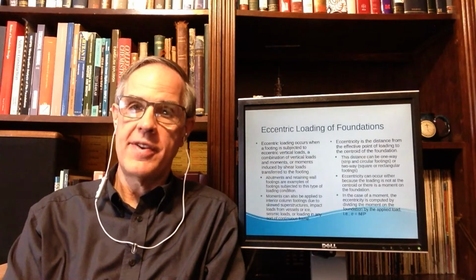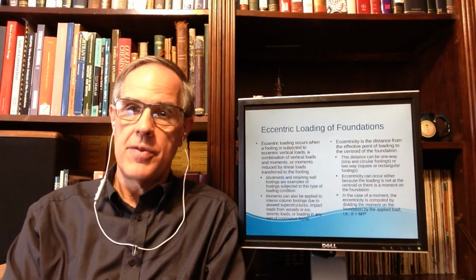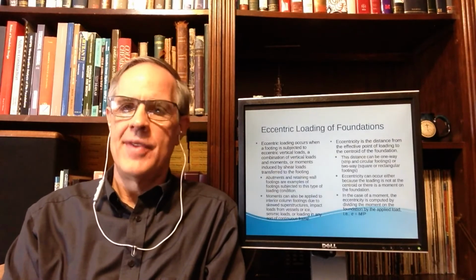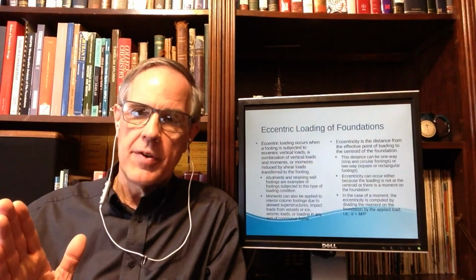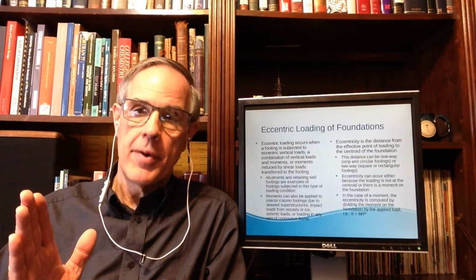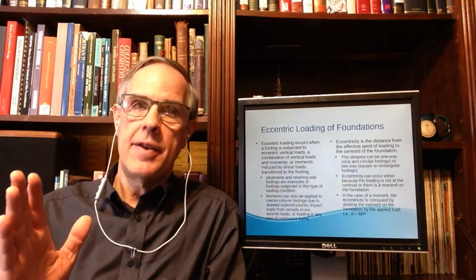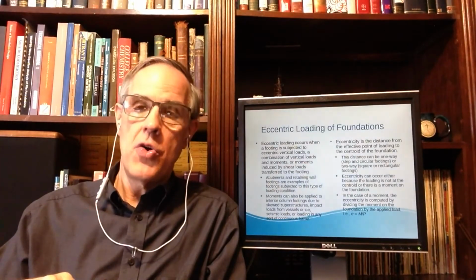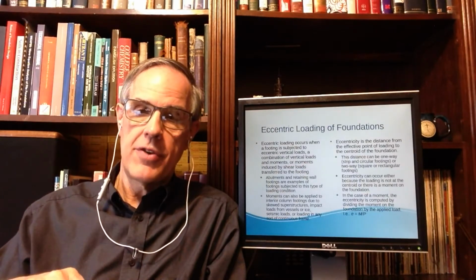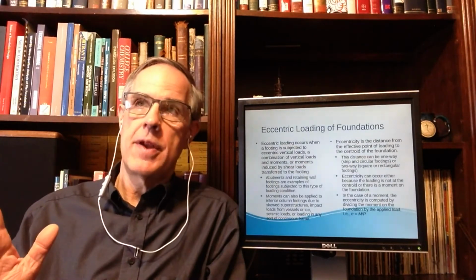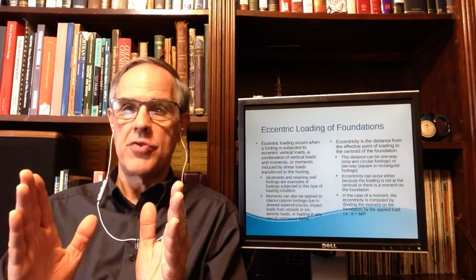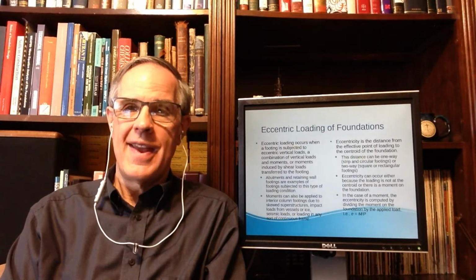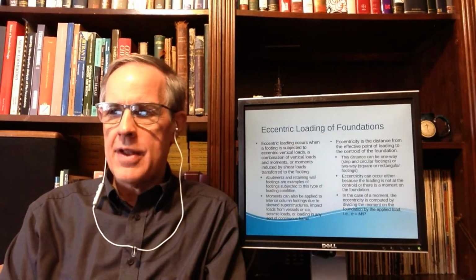In other words, instead of trying to include moments, we just say the moment moves the load. Take the moment, divide it by the axial load, and the eccentricity becomes the moment arm. And that's how you get moments out of the system. And that's very helpful.